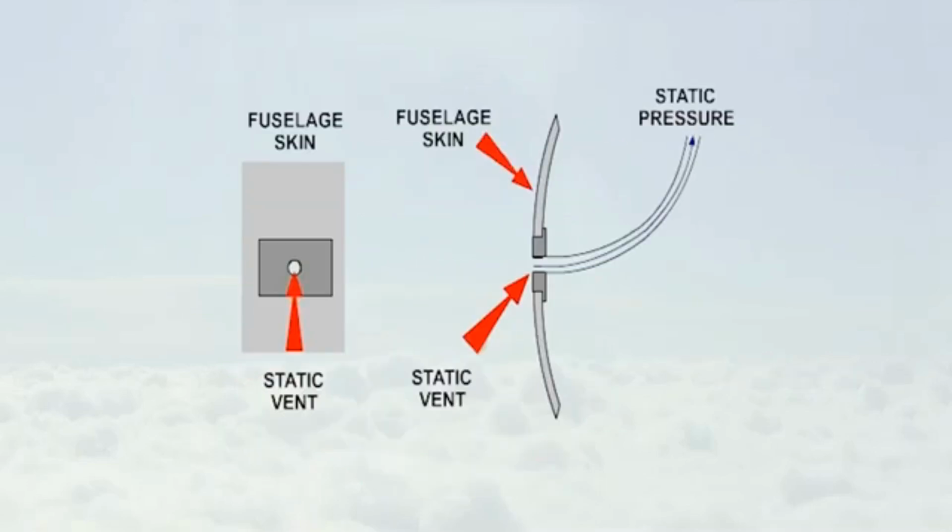Because of this, the static vent was introduced as a source of static pressure instead of the static head, pitot pressure then being sensed by a simple pitot head. About 90% of the combined pressure head position error is eliminated by use of a separate pitot head and static vent. A separate static vent is shown here. There is usually some place on the airframe, usually on the side of the fuselage, where true, or nearly true, static pressure obtains over the whole speed range of the aircraft.